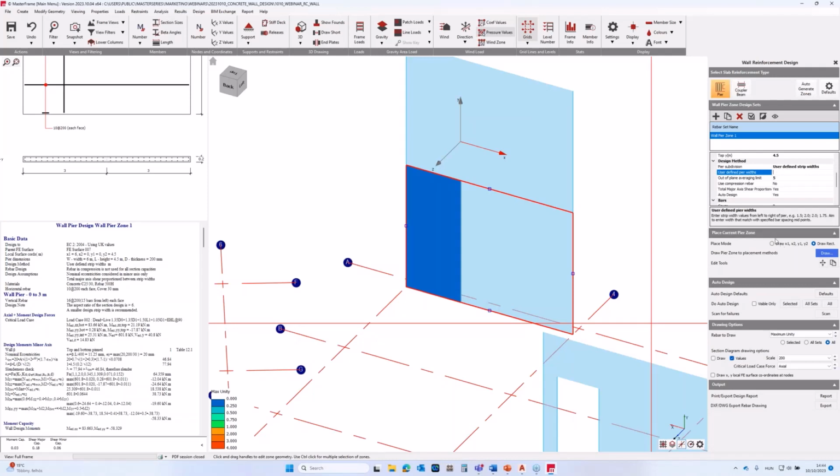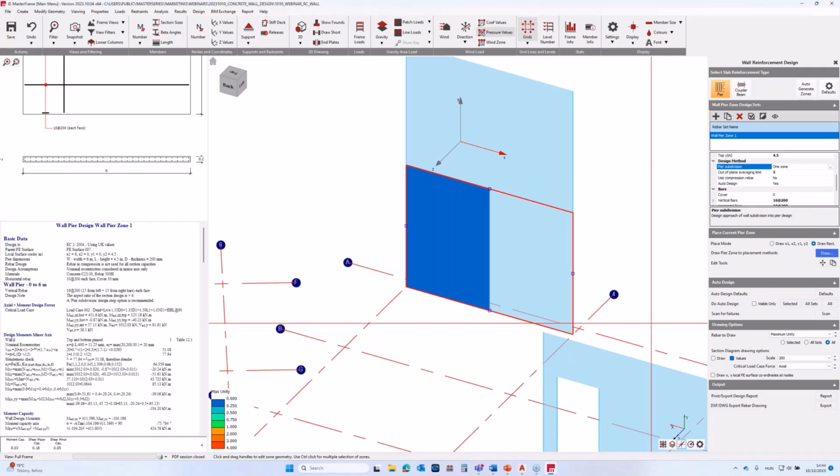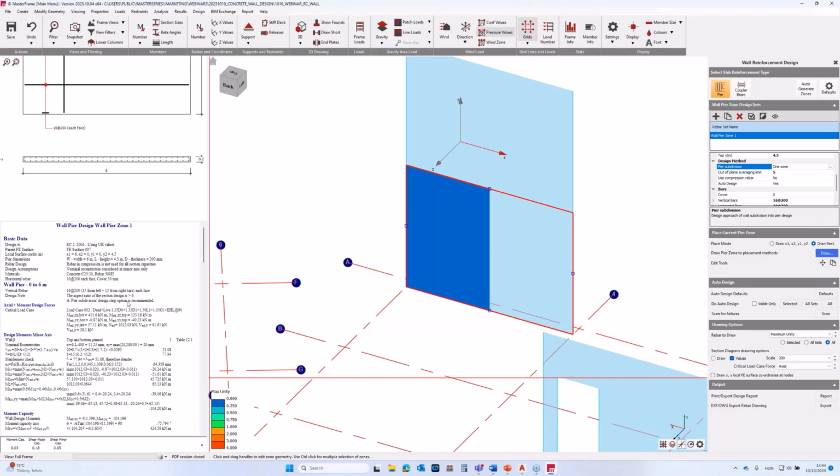Okay, we do also have the one-zone design, as Patrick mentioned, which takes everything as one zone. This method is appropriate if the aspect ratio is smaller than 6 by default. This is not the case here, so we can see a note in the detailed design saying using the one zone method is not a good idea. However, this is useful to see